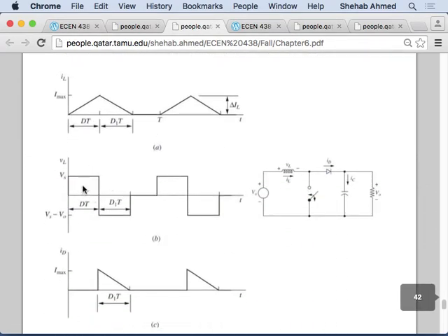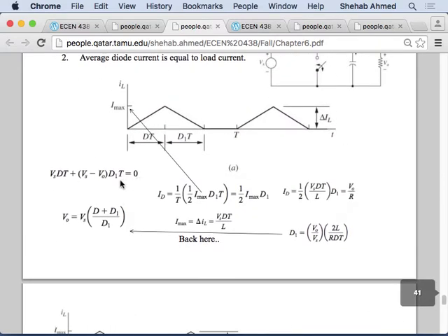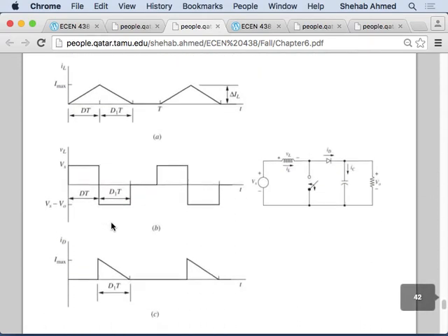And here it's the same. They're just reiterating the fact that the volt-second balance across the inductor has to exist. So this area has to equal this area, and that's how they were able to write this volt-second balance equation, from which they found the voltage transfer ratio. And sizing the inductor is exactly the same as well. It depends on the area under the curve and your delta ripple spec. So I didn't say anything new. We just introduced a new variable, D1, and it does not equal 1 minus D. That's all really. This is really what I care to talk about regarding discontinuous mode.